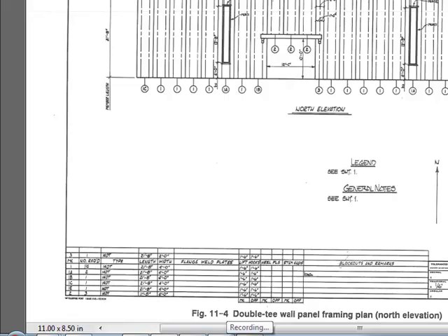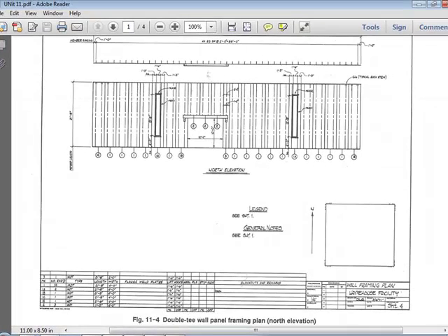And then the block out, what I was talking about when there's a window or door, is an opening left in a precast member for whatever reason: a window, door, skylight, conduit, ductwork, piping, all kinds of reasons. And they make those simply by taking the form and blocking it out with some styrofoam or wood so that the concrete doesn't get in that area. But you do have to know the size and dimensions of it.